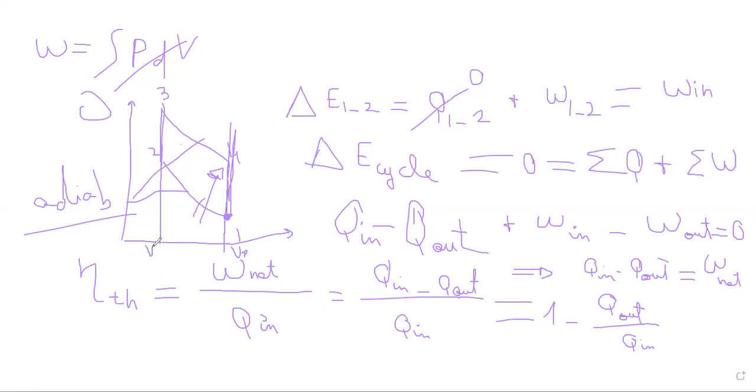In general, one very important factor that characterizes a certain engine, and it will be affected by whether it is a diesel engine or a gasoline engine, is epsilon. And epsilon is just the ratio V1 over V2. We will demonstrate now together that the larger this ratio, the larger the efficiency of our system. We will try together to relate the efficiency to epsilon.